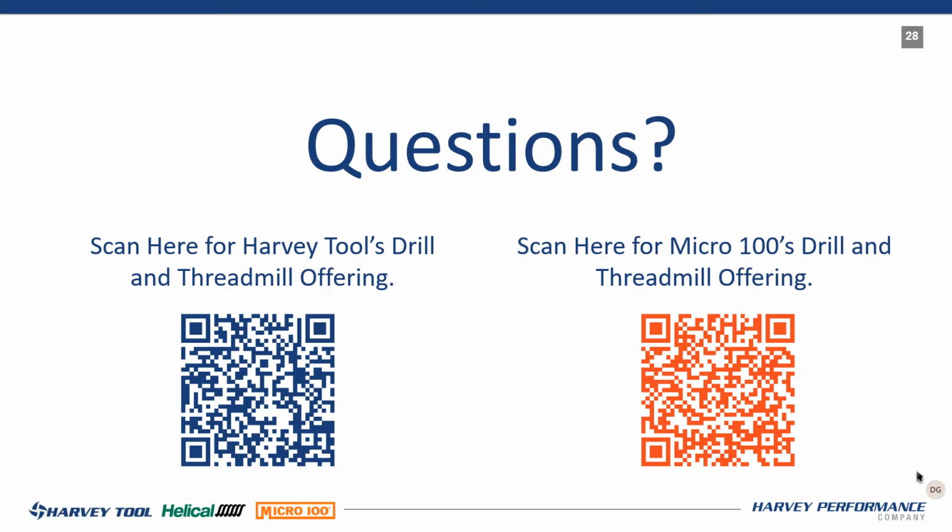So if you're pecking in a hole, reducing that peck, I know it does add some cycle time, but like I said, what's the alternative if you're breaking drills and it's a deep hole? So I would tell you right there, over 5 times D, depending on what the material is and what the chip looks like, at least 50% of that diameter. And then if that's a 12 times D drill and you're going down that far, you might look at 20% of that diameter to actually get through it. And if you're doing micro drilling, you're starting at 20% of the diameter without coolant through.